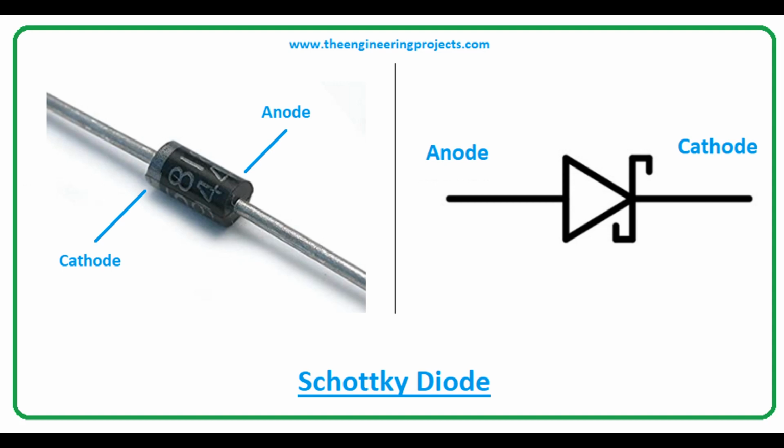Key characteristics and features of Schottky diodes include low forward voltage drop. Schottky diodes have a lower forward voltage drop, typically around 0.2 to 0.5 volts, compared to standard p-n junction diodes, with around 0.6 to 0.7 volts. This lower voltage drop reduces power losses and makes Schottky diodes suitable for high-frequency applications.